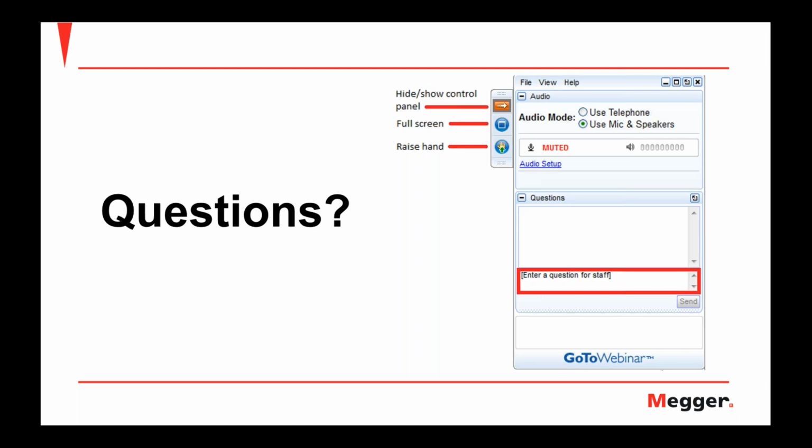Okay. The next one I see is, can we measure the ripple current using a normal clamp-on amp meter on AC mode? Yes, you should be able to do that. The only thing you want to watch out for is to make sure you have the proper bandwidth on it. I'm going to be pretty honest, pretty much all of them should have the proper bandwidth. However, if you do have a lithium ion string, you want to make sure that bandwidth can get up to about 10 kilohertz. Other than that, you shouldn't have an issue with doing that.